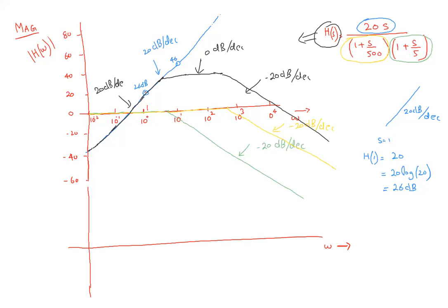So first of all start with the 0. What is normally the phase of a 0? We know it's going to be positive. If we have one 0, by the end it should be 90 degrees. Now what is happening? The 0 is at origin, so since 0 is at origin, we don't know how many, 0.0001. So this means from the point 10 raised to power -2, the 0 will have a phase of positive 90 degrees. Let me now draw the values. So this is going to be 90 degree, 45 degree, 0, -45, and -90 degree.